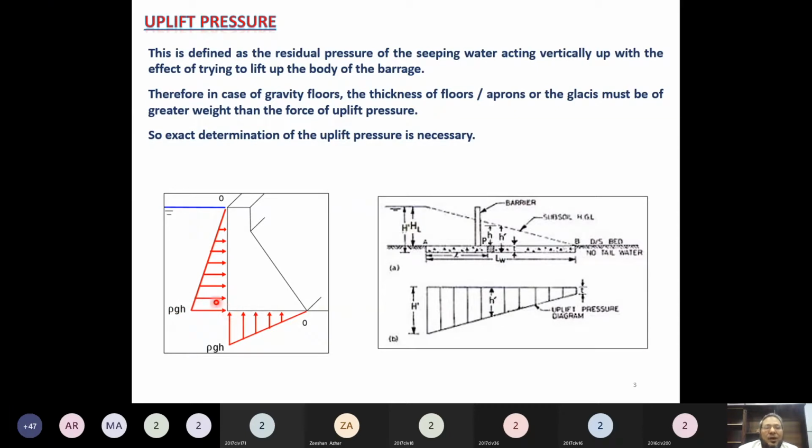And how much would be the hydrostatic force which the water is acting on this dam face, that we have studied in detail in the subject of hydraulic engineering? What is the magnitude of the force? Also we have studied it in fluid mechanics 1. That is gamma A h_c. Is it okay? Yes, sir. Okay. So the pressure at the bottom would be highest, and that is gamma times H.